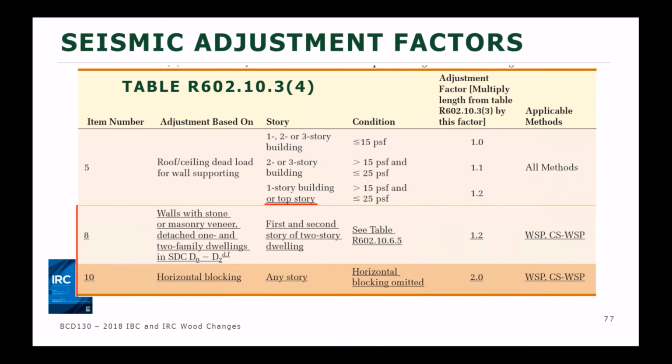Occasionally somebody has a single family home where those sidewalls are very short and they just don't want to deal with the blocking. They've got a 10-foot tall wall, all their panels are 4x8s, and so they can choose to have on these sidewalls where there are a few windows just twice as much, and it works fine.